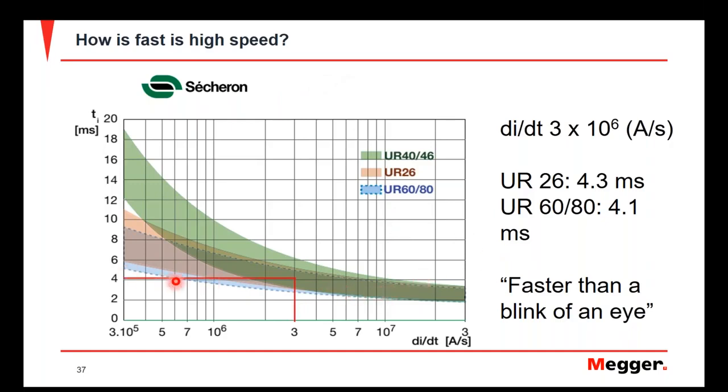in relation to the rate of rise for current during a fault, this is how fast your current can rise, at as much as 3 million amps per second, as far as the energy that's developed whenever you have this fault condition. And at a rate of rise in relation to this, the breakers are designed to trip within 4 to 5 milliseconds to be able to respond quick enough to limit that amount of fault energy that can be created from that overcurrent condition.